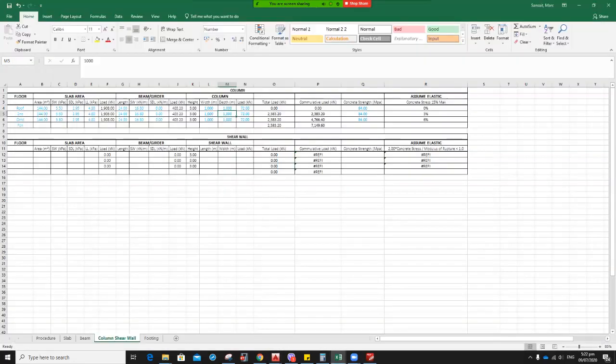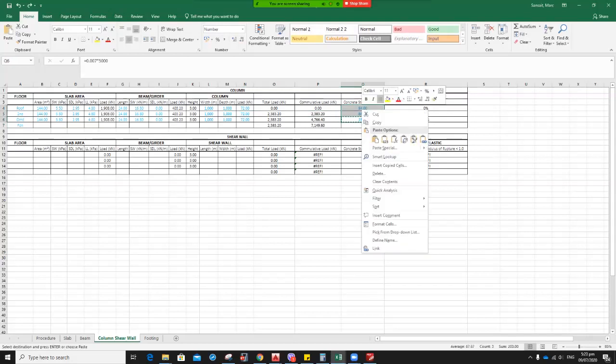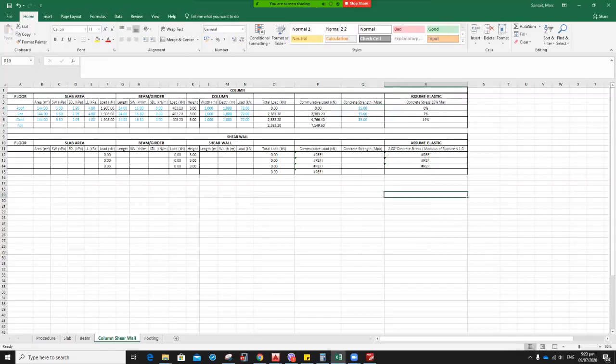Okay, now let's start to reduce the mean to get the 6. So what we can do to make it easier, 0.007 times the concrete strength, maybe 5,000. Okay, 5,000 is working. 4,000 is not. So maybe we can use 5,000 psi concrete. Okay, doing that, can try.